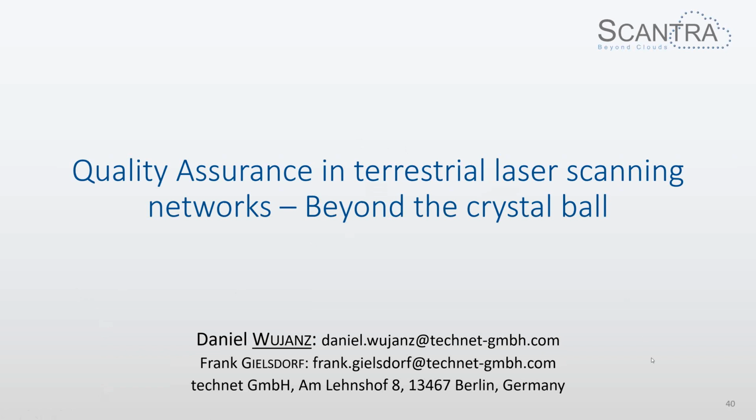The question is, if we compare TLS versus SLAM-based laser scanner, how can you compare the strategy of your algorithm compared to the SLAM algorithm's philosophy that tries to minimize the drift, the loop closure? First of all, thank you very much for the question, because we're actually working in this field. We just talked about static or terrestrial laser scans. But you can also apply the principle of loop closures to kinematic scans, and we are also doing this. I will try to answer this very briefly, but I will send the person who asked the question a more detailed answer, because I have to admit this deserves another webinar.